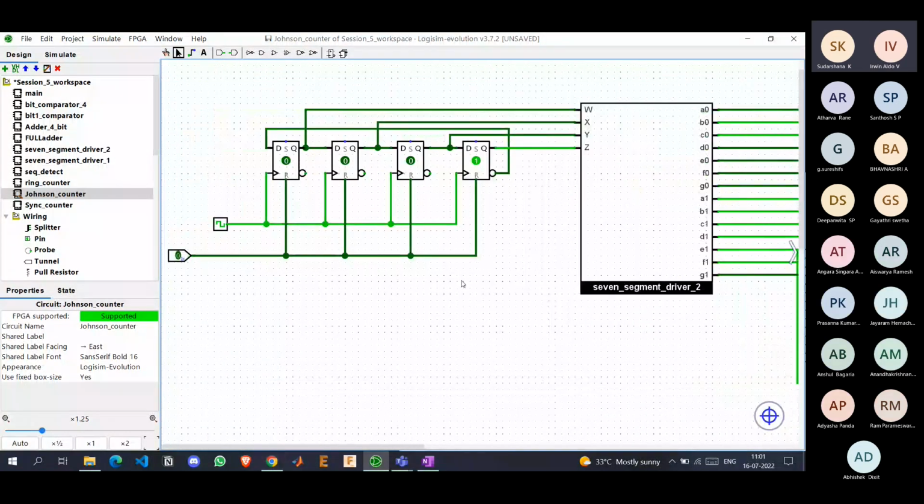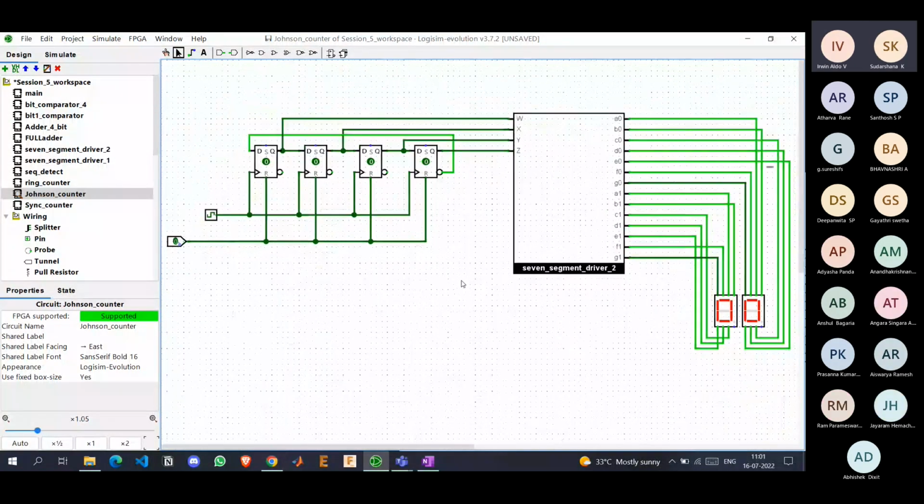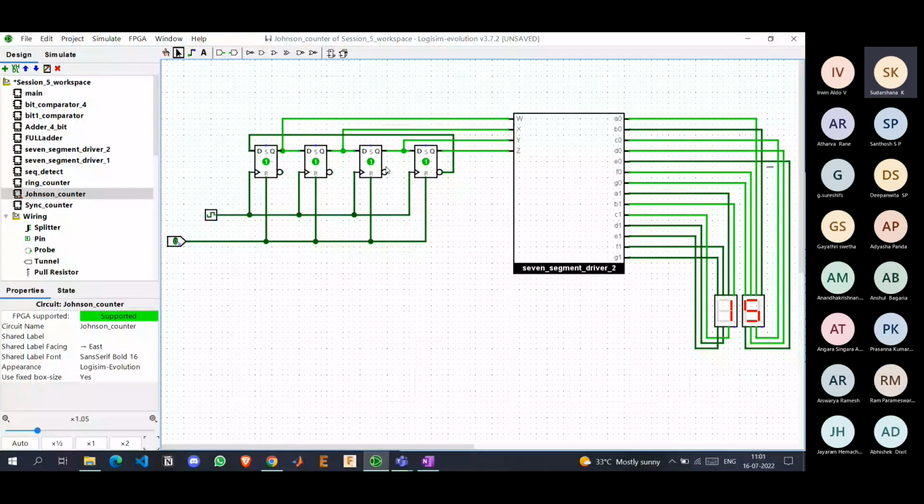You guys understood how a Johnson counter looks like, right? How it works, with a slight modification to the ring counter we saw earlier. You can build the Johnson counter and ring counter from scratch using those state diagrams and tables, just by providing the exact value, the exact path of the movement.